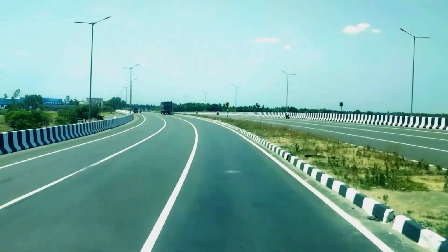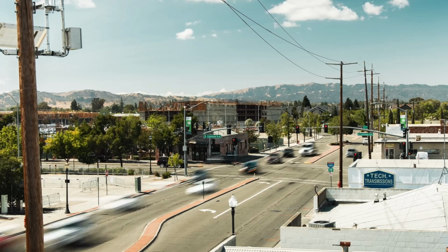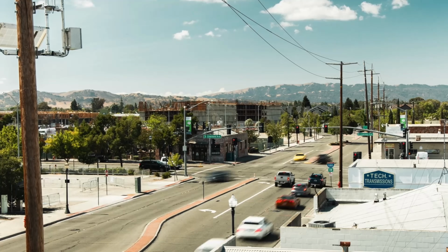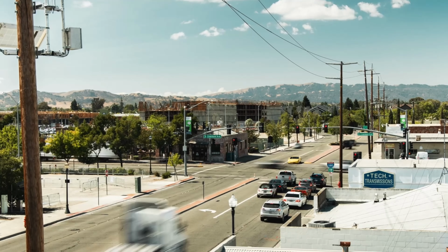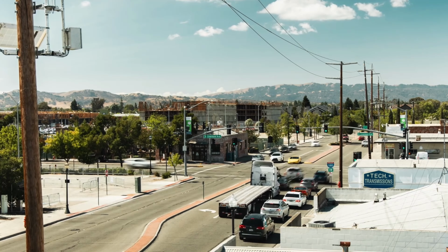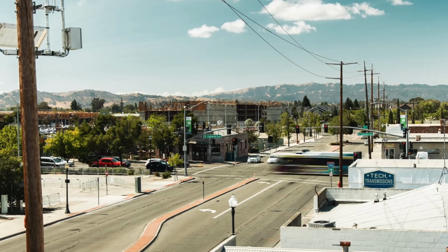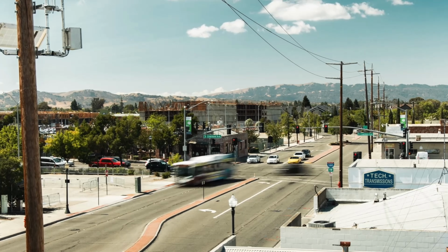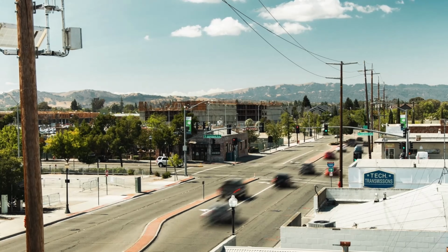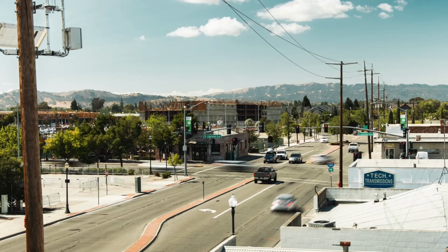At U-turn locations, adequate storage space must be provided for waiting vehicles. Otherwise, traffic may spill into moving lanes and create dangerous conditions. Openings in medians should never be introduced randomly. Particularly, openings in medians should not be introduced at the point of small link roads. Improper median openings are one of the major causes of highway accidents.